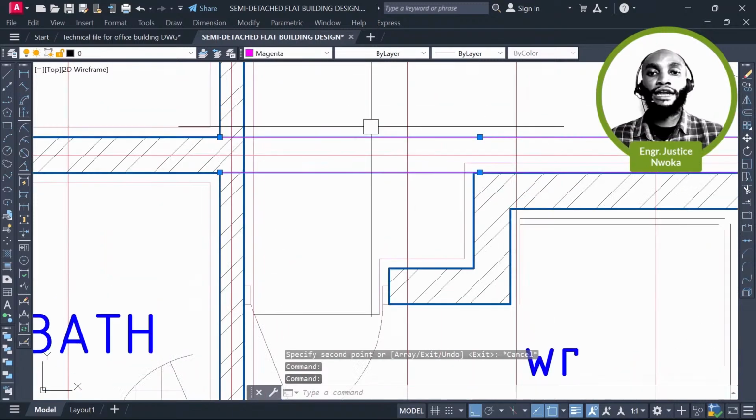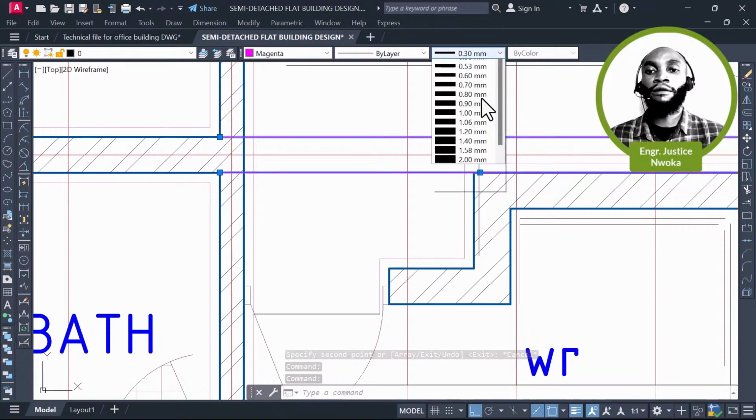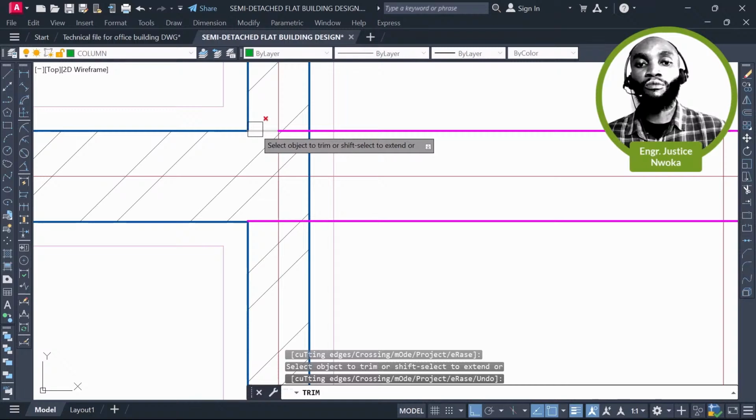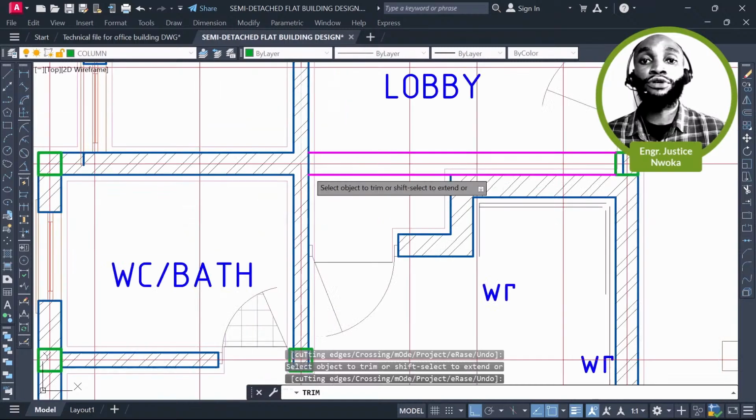Anywhere I see this kind of color of wall, I'll know that this is for an internal beam, which will not carry wall load, because it does not have wall load. So with this now, I'm running my beam all the way down from here to here.